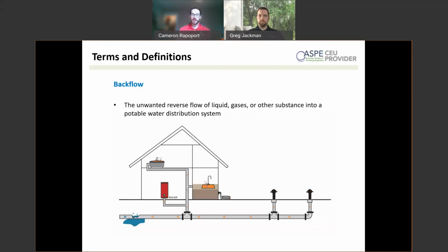What I always tell people when I'm explaining backflow to them is that our water distribution system is built to operate in one direction. And when the direction reverses, you have a problem, especially when you have cross connections and contaminants downstream that are unprotected by backflow preventers. So in this case, a water main breaks. It has the potential to siphon any number of contaminants out of this building, out of the lawn sprinkler system. If you have dirty water in an unprotected sprayer submerged in a bath or a sink, stagnant water or glycol in the boiler, static water pools or fertilizer in the sprinkler system, that kind of stuff.